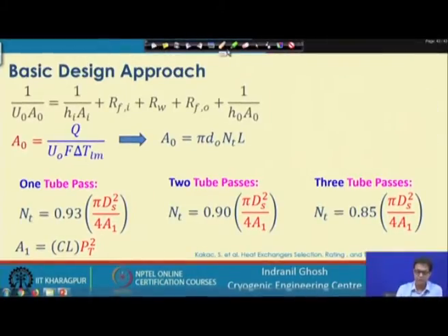If we have the heat transfer known, that is the heat duty, we have the delta T LM known, because in a design problem all the exit temperatures are known. This F factor we generally assume to be 0.9 or around, because in a counter current exchanger it is 1, but it is not really a counter current exchanger, and the actual value of the F